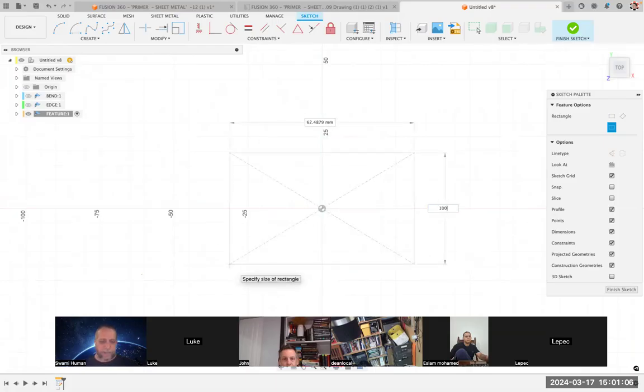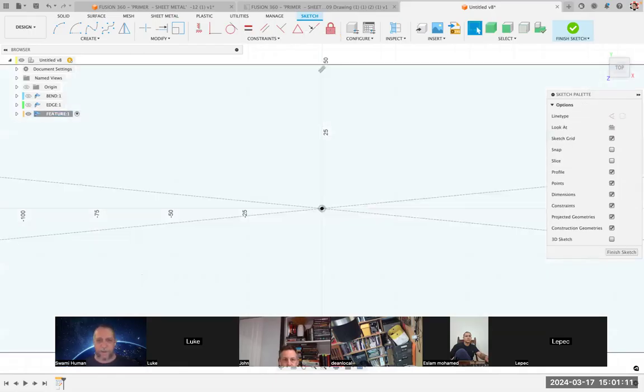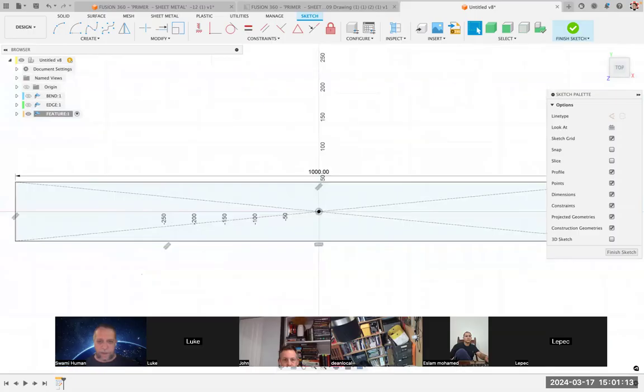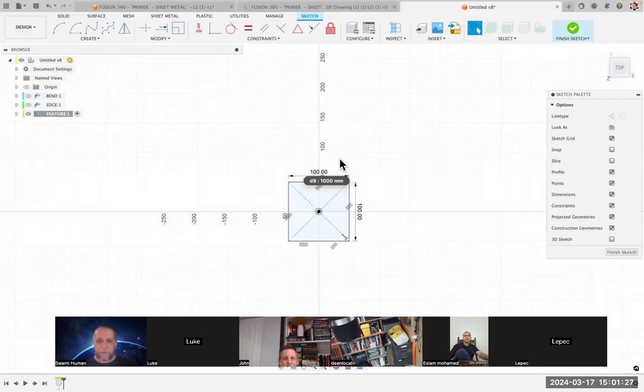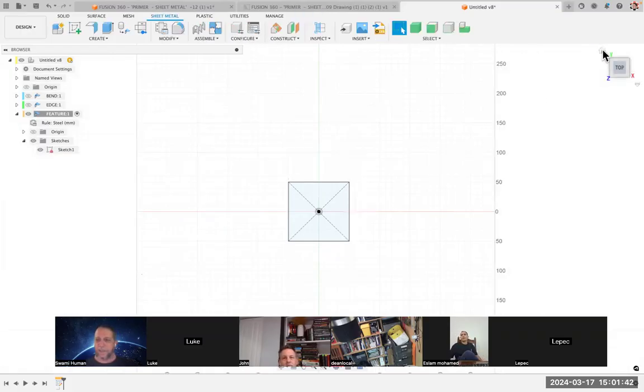There's going to be 100, tab 100, enter. I missed it, so I'm going to alt double click out here. Oh, my keyboard is bouncing, by the way, so I got an extra 0 in there. Let me go ahead and edit that 1000 down to 100 and take a look. There we go. All right, so now we have our 100 by 100 over here, and that should be locked down. It's a simple rectangle tied to the center with 100 on each side. And now we're going to say finish the sketch, get a home view.